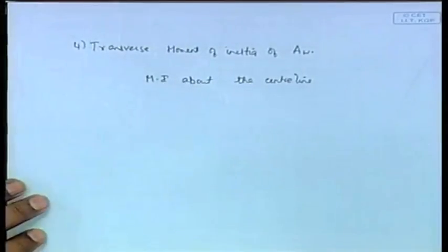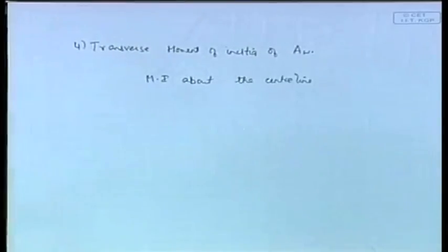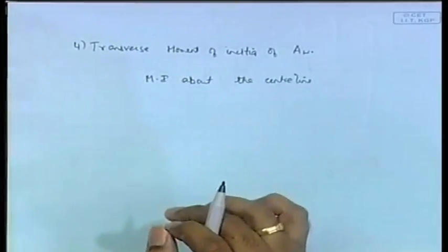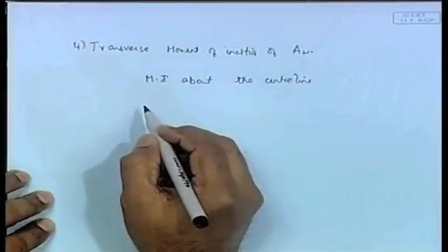You keep forgetting this, but remember, this is the longitudinal axis, there is no doubt about that. Longitudinal and transverse direction should be very clear. If the transverse axis is clear, then transverse moment of inertia has to be in this direction. So you actually need the distance in this direction, and this distance can only be from some fixed line like this, which should be your longitudinal axis. So that is the meaning of transverse moment of inertia.